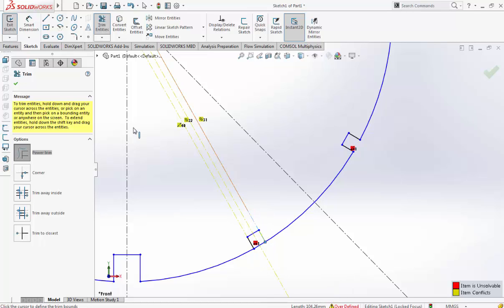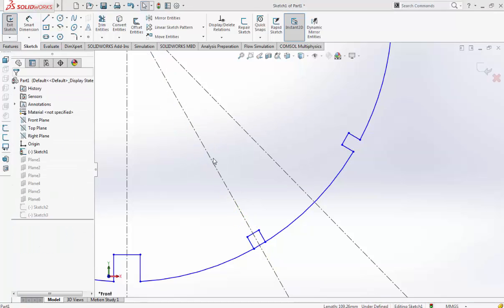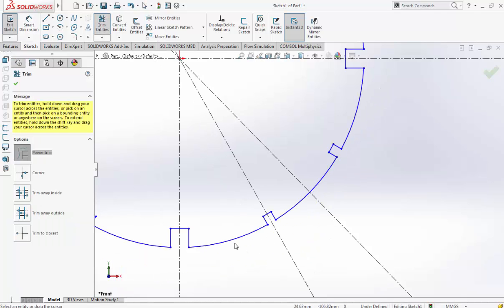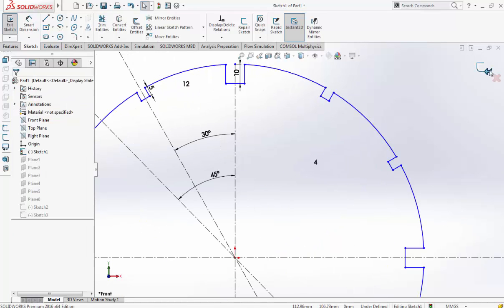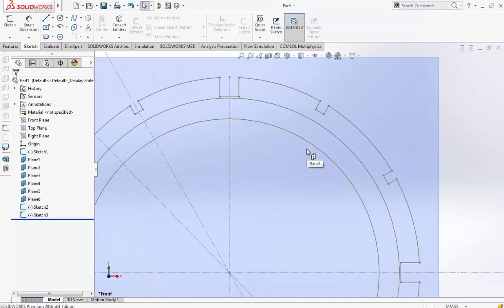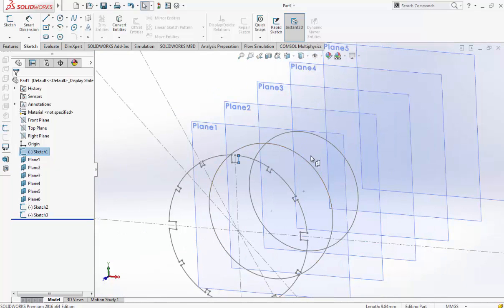Yeah, this happens because these are all the lines. Okay, so this is the first one. Don't try to scale this drawing in sketch 3 or sketch 2 because you will scale also this dimension, and you have to maintain the same dimension from the first to the last former.